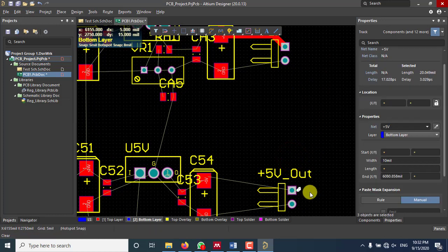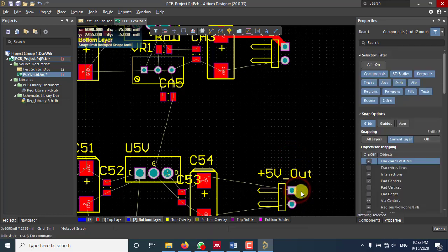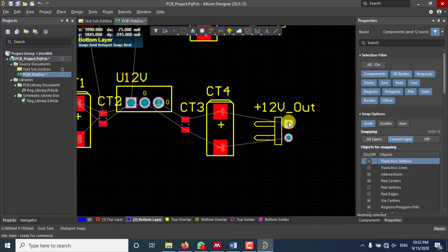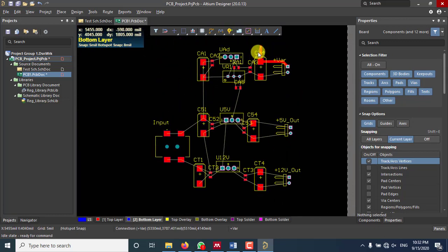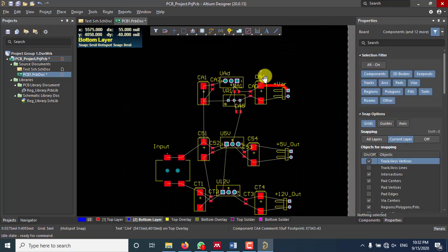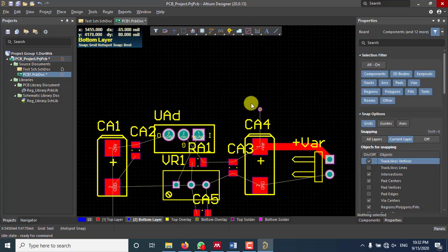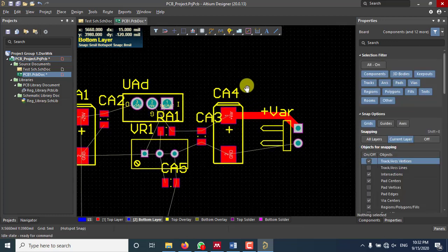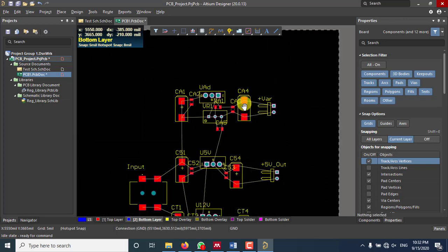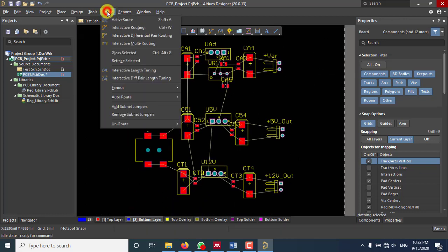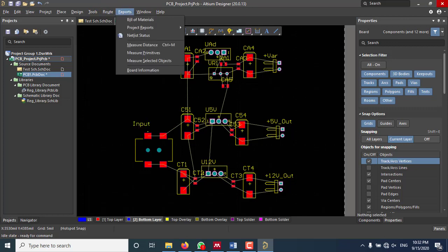The one thing you might have heard of is the automatic routing. Okay, and that's quite straightforward. You can use automatic routing, but that's not always useful, because there are some tracks that you want to be closest. You want them to be preferred while routing, but they might not be.